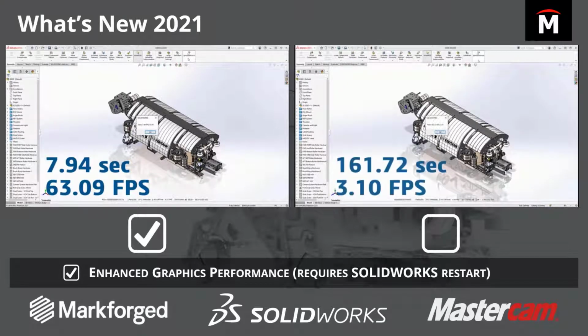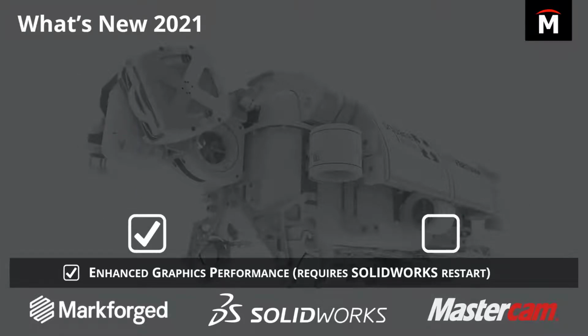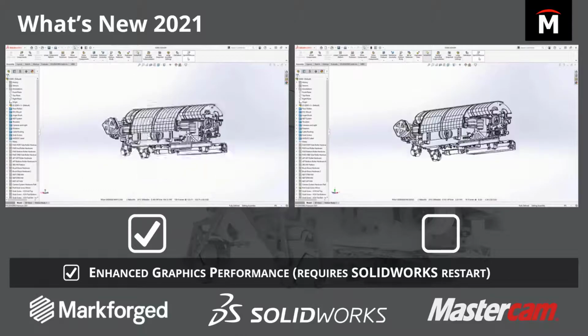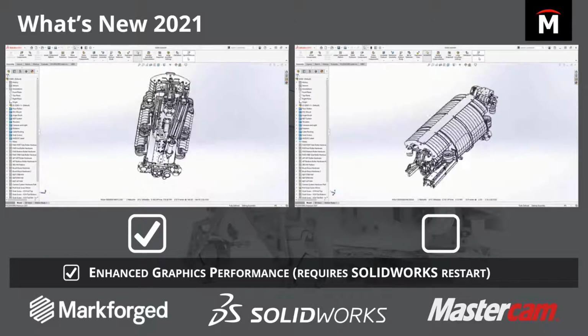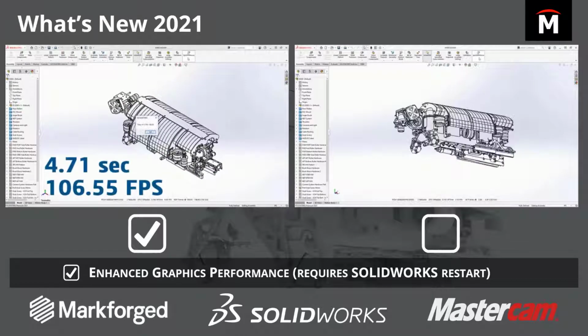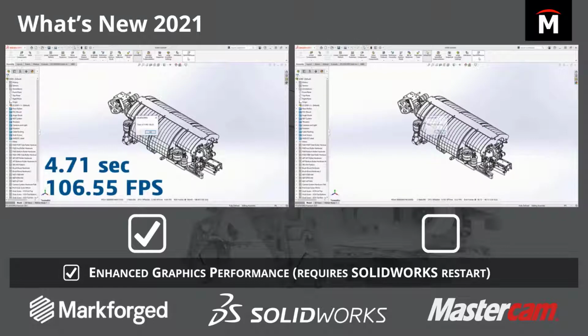This is a system option that was first introduced in SOLIDWORKS 2019, but beta mode is now over and it's enabled by default. If you're running a supported graphics card, you should see an immediate improvement in model rotations, particularly when working with large assemblies. You might not know this, but previously calculating silhouette edges and hidden lines removed and hidden lines visible was performed by the CPU. This task is now handled completely by the GPU and produces huge gains in frame rates and rotation speeds.